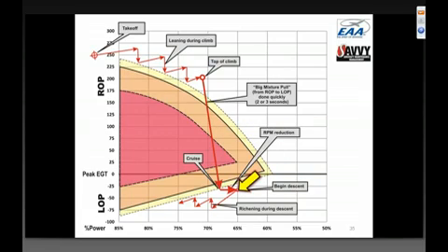So at any rate, now we're in a nice lean of peak cruise, and we cruise along until it's time to descend. When we start to descend, we typically just push the nose down, and then as the aircraft descends, if it's normally aspirated, the mixture will get leaner in the descent, and we have to compensate by pushing in the red knob from time to time until we complete our descent. So that is sort of the way we travel around this red fin.